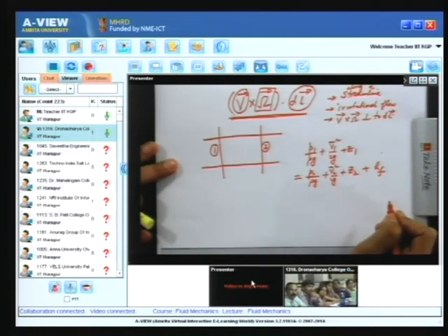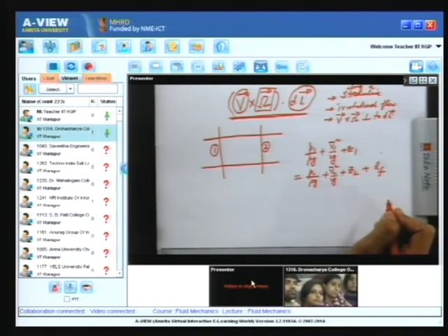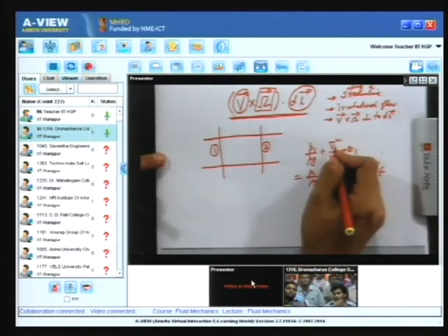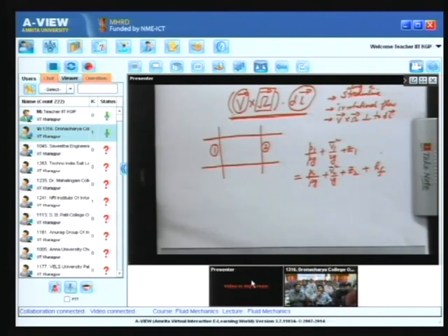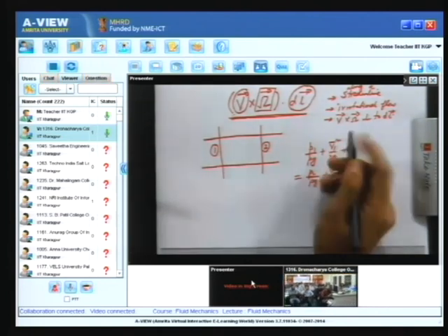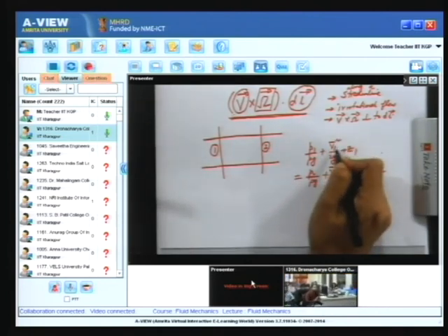Average velocities, not velocity at points 1 and 2 which are there in the Bernoulli's equation, but the Bernoulli's equation is applied between 2 points. Here the equation is applied between 2 sections, so V1 and V2 are average velocities. Now by these 2 terms we are essentially trying to represent the kinetic energy, but with the average velocity it may not be accurate to represent the kinetic energy.